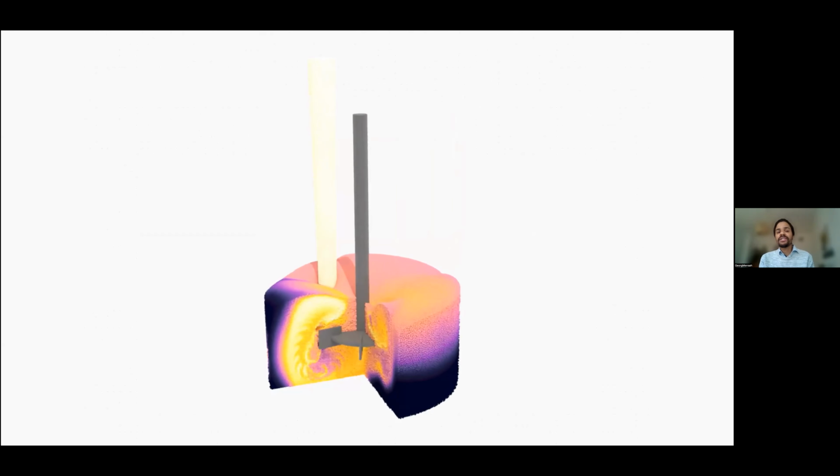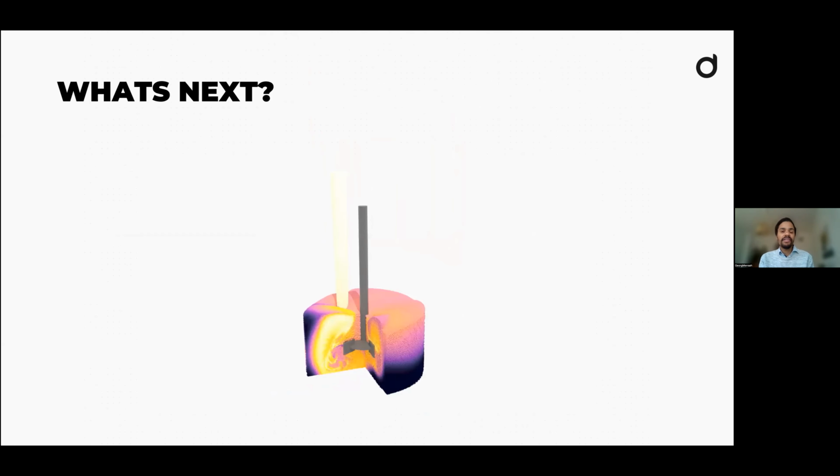What's interesting is that once you have done all the effort in developing these models, you realize, hey, I have a transport equation, and it was initially meant to model thermal behavior and how it interacts with the viscosity. But as it's a transport equation, who says that this color coding is temperature? What you see here is actually mixture fraction. So you use the parabolic equation that you already implemented, developed, and tested for thermal modeling to also model other effects like diffusion. This is really something that you get for free in the end once you did all that.